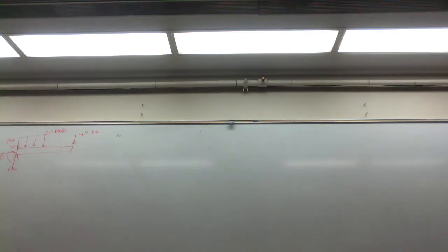Okay. So if we sum the forces in the y, we can jump ahead and do that immediately. Sum the forces in the y, we can solve for Ay. So we have Ay minus 40. Think back to module 3 with our distributed loads. How do I represent this as a single force? Length times width. Take the area under the curve. We can do that by integration. We learned that method. But we can also just take the area under the curve because we're given the dimensions.